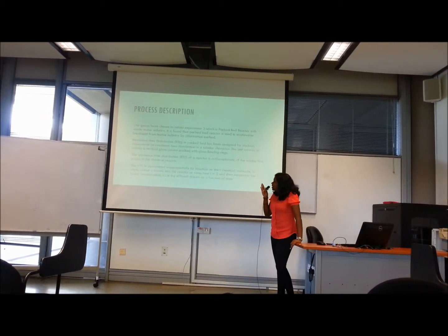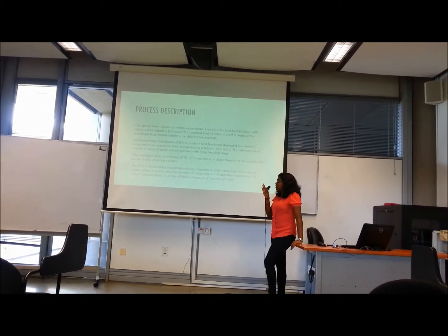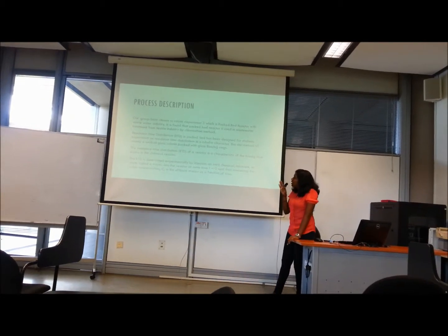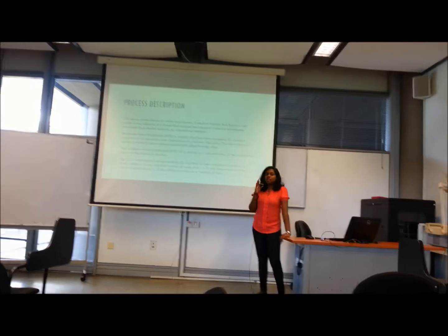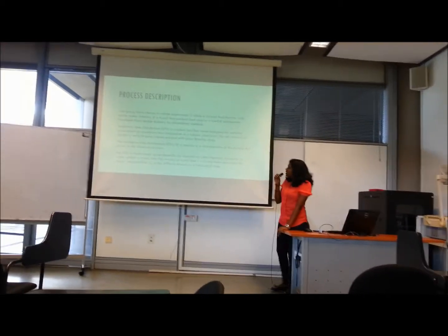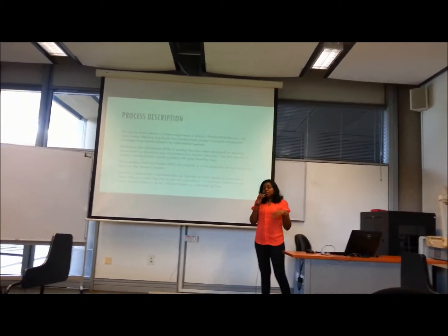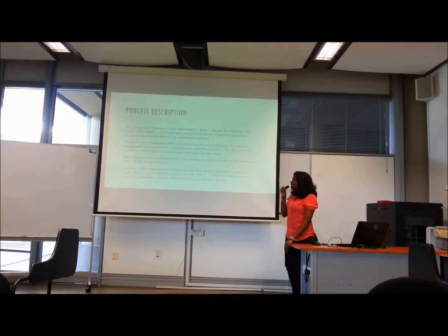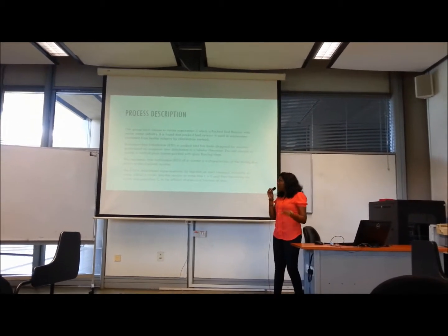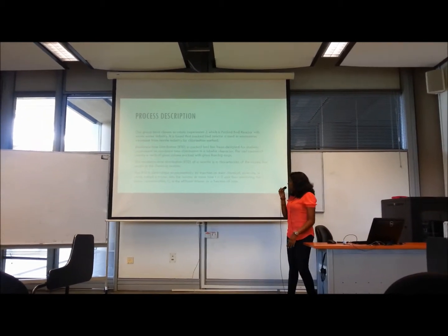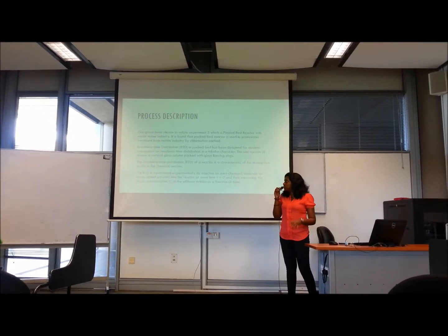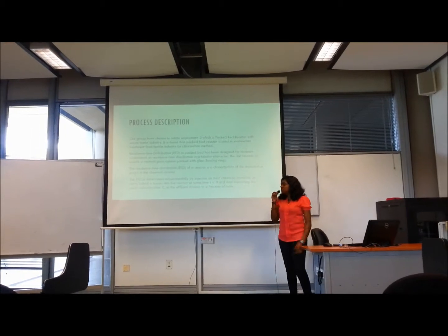And the residence time distribution, which is RTD, of a reactor is a characteristic of the mixing that occurs in a chemical reactor. The RTD is determined experimentally by injecting an inert chemical molecule or atom, which is called a tracer, into the reactor at some time, and then measuring the tracer concentration in the effluent stream as a function of time.